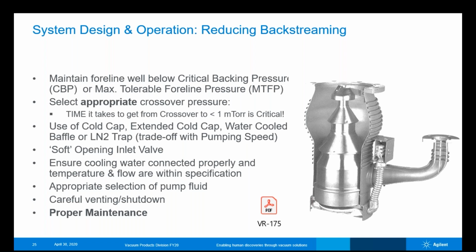Cooling water is very critical in diffusion pumps. We need to maintain that the water is connected correctly, where the inlet and the exhaust of water are connected appropriately, and also that the temperature and flow are within the specifications for the individual pump and the type of oil that we're using.